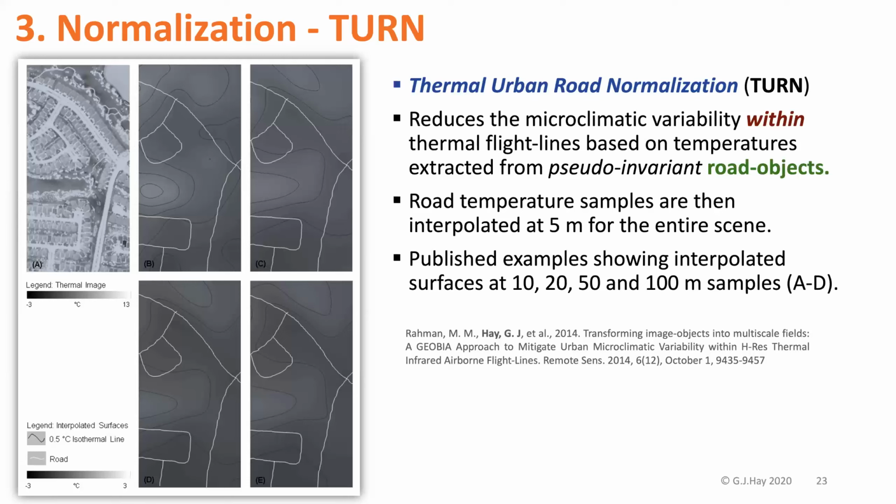The reason we do this is because it allows us to collect under very different environmental conditions and on different dates. This will allow us to normalize to a common road temperature, so all of the data sets that we use can be evaluated together. Otherwise, the data sets cannot be evaluated together.